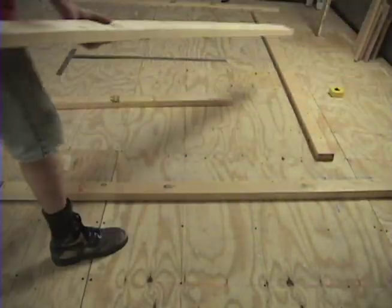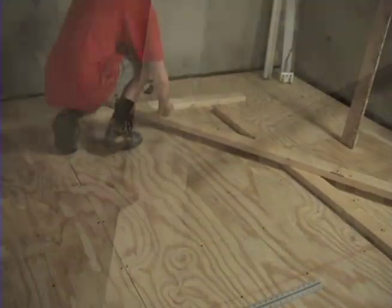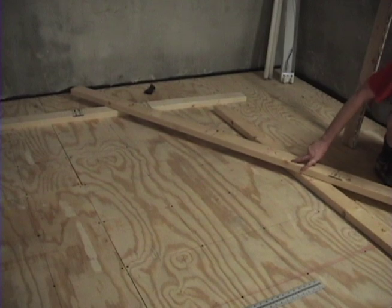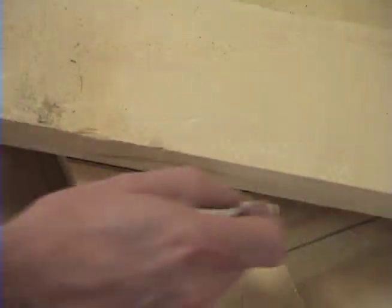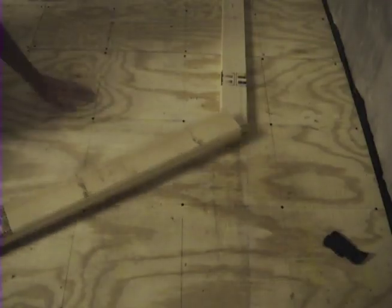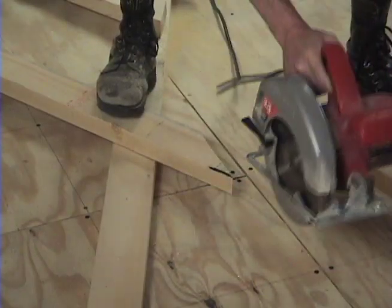Now we lay down a 2x4 at 205 inches on the left wall, and then 205 inches on the right wall. And where they cross the center line, that determines the angle. By design, it should be a 60-degree angle, but in actual construction, our angle is 61 degrees. With these 2x4s in place, you can mark the angles to cut on the wall plate, and then for the angle plate, referenced against the front wall chalk lines we drew earlier. Make the cuts with a circular saw, and the puzzle fits together nicely.